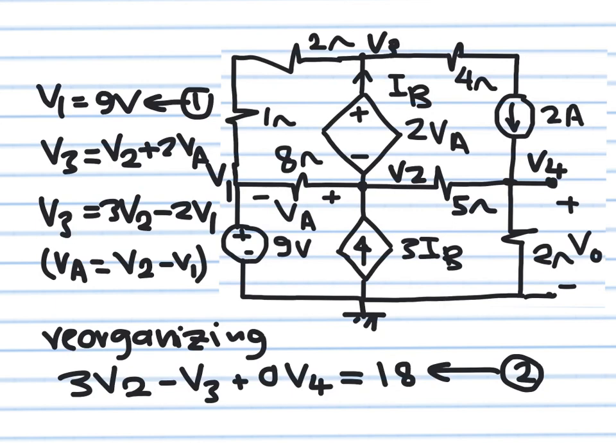And then every equation I'm going to write in order. Okay, so the first equation I can get from this voltage source is that 3V2 minus V3 plus 0V4 is equal to 18. Now, I need to get a second equation because this voltage source stopped me from writing KCL here and writing KCL here. So I lost 2 pieces of information. I got one already. The second one you'll obtain, as we learned from class, is by forming a super node. You form one big node to enclose that source, and then you say the sum of all currents flowing out from this node is equal to 0.